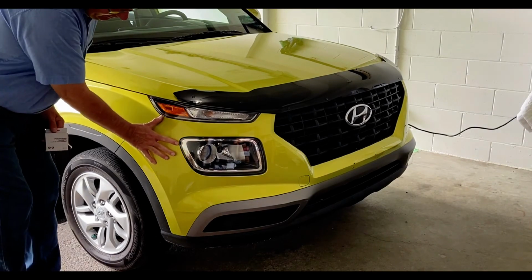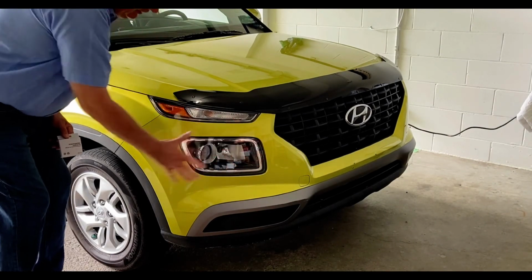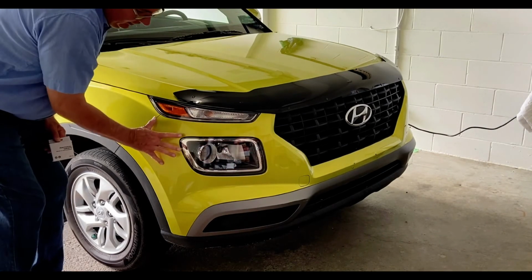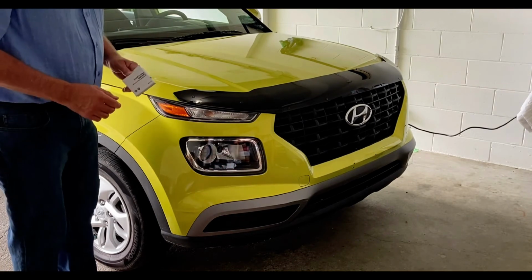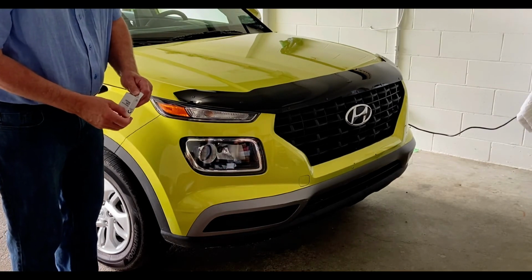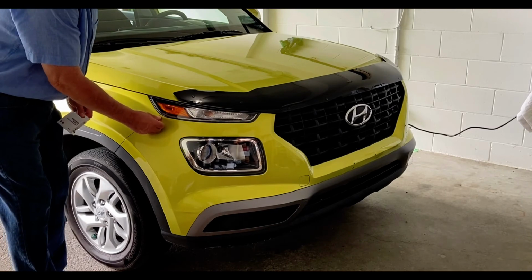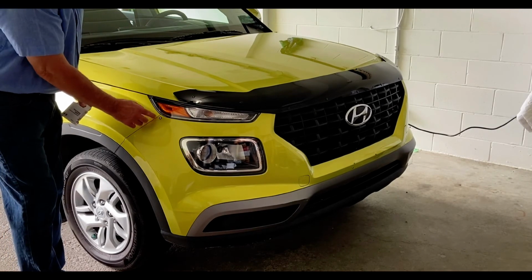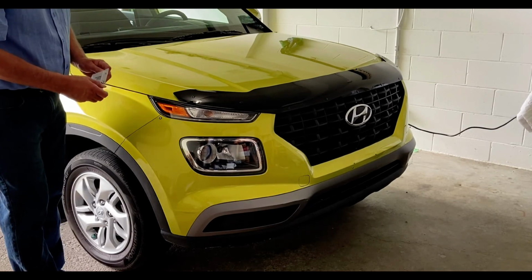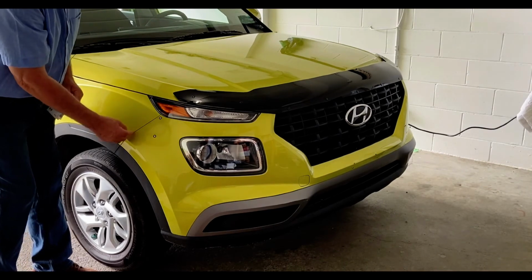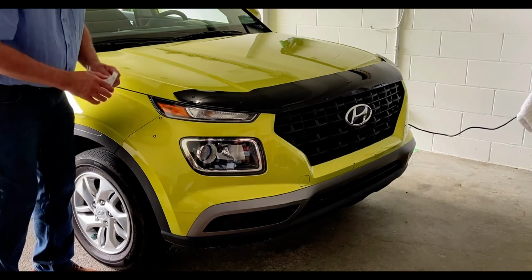Now it's time to place scanning targets on our surface area. We use a hand span as a general guideline for how to array our targets that we place on the surface area. You can see that we also want to make sure that we're placing some targets that are close, but not necessarily on the boundary edges of the surface area that we want to scan.